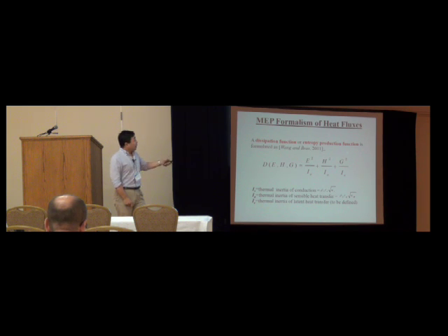So if we formulate the dissipation function in terms of the flux squared divided by thermal inertia, then our next job is to formulate the thermal inertia associated with each of the fluxes. Again, the thermal inertia of the conduction of the soil is a physical property. It is equal to the density, heat capacity, and the square root of the diffusivity. By analogy, we can do the same thing for the sensible heat flux, except here the diffusivity is the eddy diffusivity. We need to model that in terms of turbulent flow.